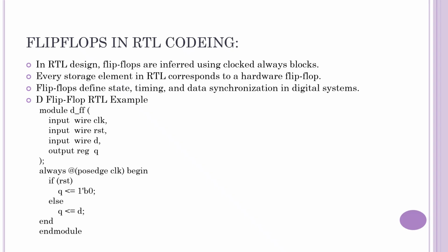So, the key RTL coding rules for flip-flops are: use non-blocking assignments, prefer synchronous reset for ASIC designs, avoid mixing blocking and non-blocking in sequential logic, and avoid incomplete if conditions because they can infer latches.